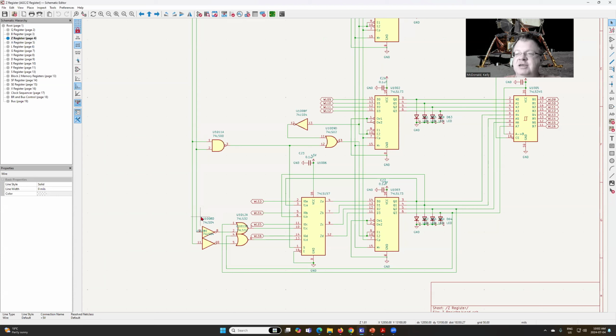And in reading the documentation and going through a couple versions, it looks like the functionality is that you need to maintain all the current contents of the Z register, and then if the Z15 is a 0 and you get that signal, we set it to 1. Likewise for Z16. So we have this scenario of, what do we load into bits 15 and 16 of our register? So this is our 4th 173, and that's basically responsible for bits 13, 14, 15, and 16.